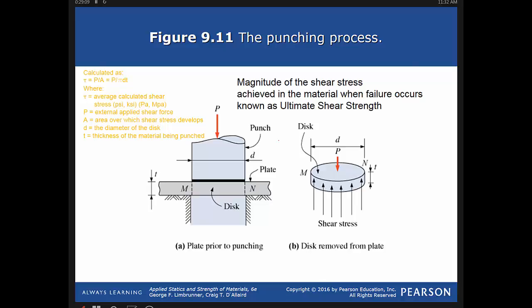Okay. Yeah, that's where I said before on that bolted connection, if those two plates aren't close together, then it's going to be harder for that to shear. Because the farther away you get, and again, think of a leather punch, and the hole on the bottom was much bigger than the die, then you're basically drawing that material down into it before you make it fail. Then it's a matter of, do I have enough room to draw that down into that hole before it shears? If it doesn't, then you're just doing what's called a drawing operation, and you're making like an aluminum cup.